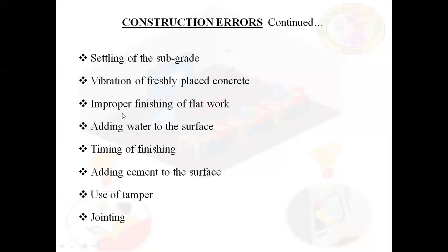Next, vibration of freshly placed concrete. That means while casting the fresh concrete, we have to do proper vibration. Otherwise, compaction will be reduced. So next, adding water to the surface. This should not be done. Next, timing of finishing, adding cement to the surface.